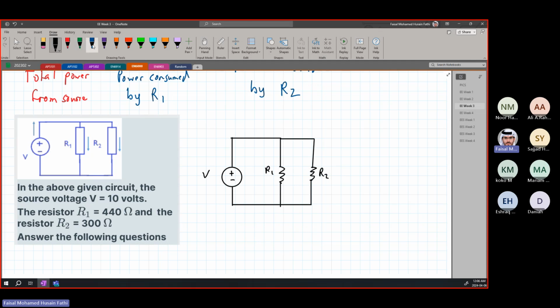If you remember in series, when I said the voltage goes across the wire and it only drops when it goes through a component, right? For this blue part, all of it has the same voltage. The whole part here is the same voltage. All right? This is all V, which is equal to V total, which is equal to the voltage source itself.